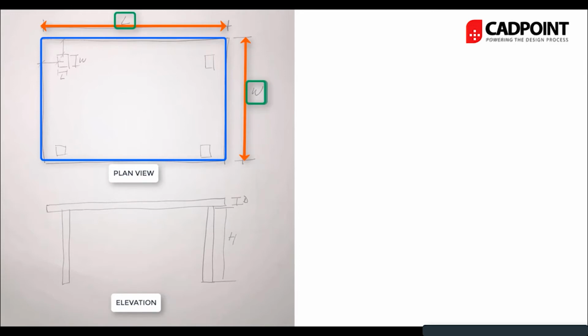So we'll create a constraint or a parameter called length, and we'll create one called width. So this just means that you can flexibly use your table. It can be any size in any project that you assign those particular parameters to. And we want to be able to control the thickness of the actual tabletop as well. If it's timber or concrete or metal, we'd be able to control it from any dimension, 100 mil, 50 mil, 25 mil. And then we're going to have 4 legs, and they'll always be placed within the table, and they'll